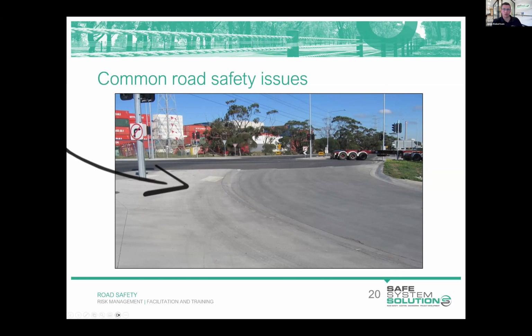It's a lot easier for a truck driver to understand whether the front of their vehicle is tracking than the rear. And particularly at low speeds, long articulated trucks cut in by a significant amount, so that the rear axles take a shorter radius path than the front of the vehicle, and you can see trailers cutting across curbs and into pedestrian areas